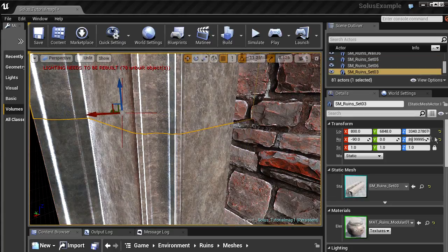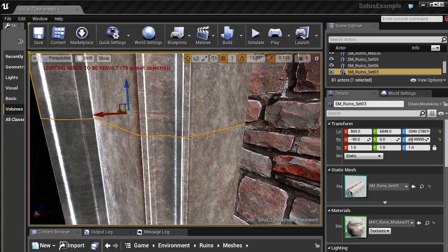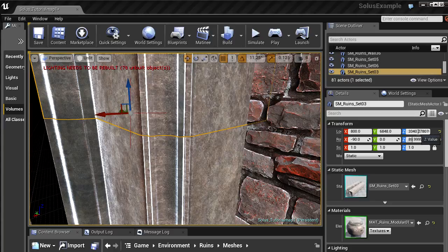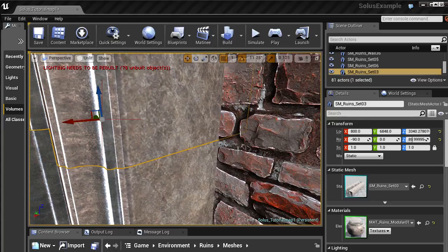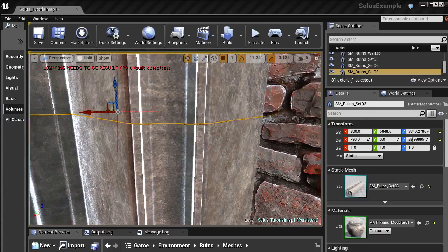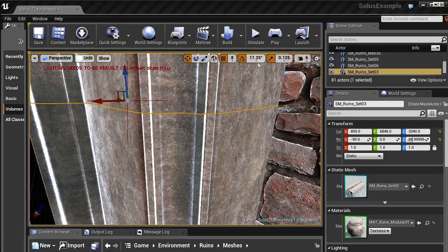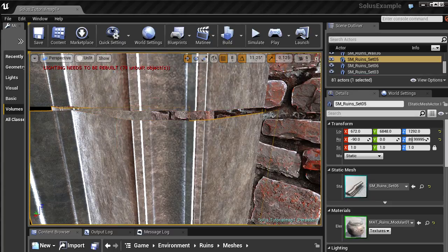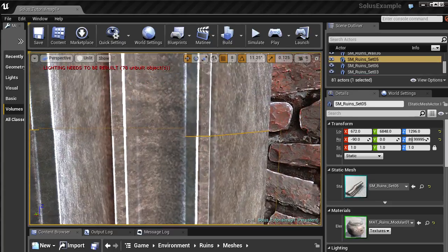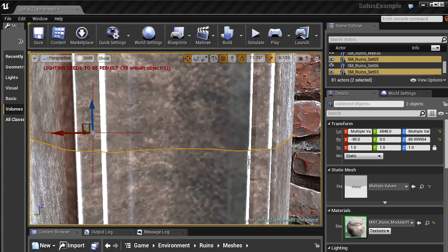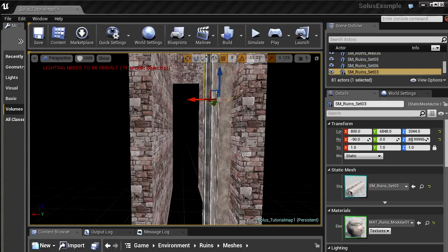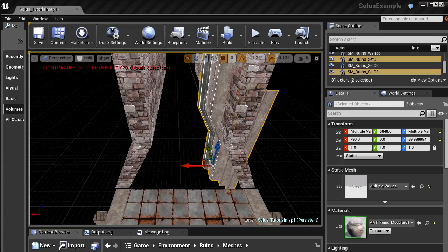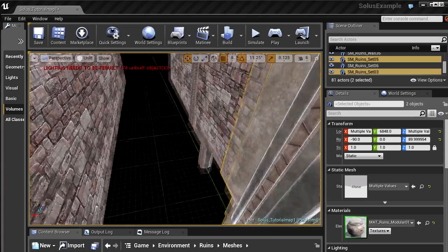If you look at the top piece, this is 3340, so 3340 with a comma number behind it. If I now do Control End, so the End key on the keyboard, you can see it snaps to the nearest grid point. If I increase the grid, see the grid's now increased to 8, and I do it again, it snaps to the nearest grid point of 8. And if I do the same with this one, it instantly fits together. Okay, so that's that. Let me copy the thing over.